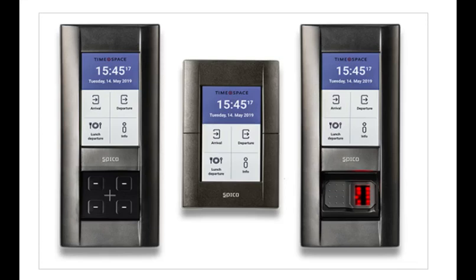When an object, such as a fingertip or stylus tip, presses down onto the outer surface, the two layers touch to become connected at that point. The panel then behaves as a pair of voltage dividers, one axis at a time. By rapidly switching between each layer, the position of pressure on the screen can be detected.